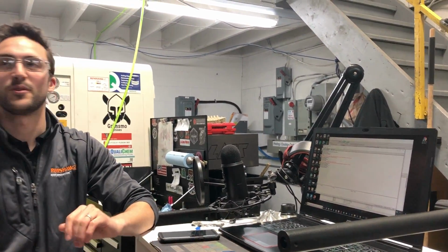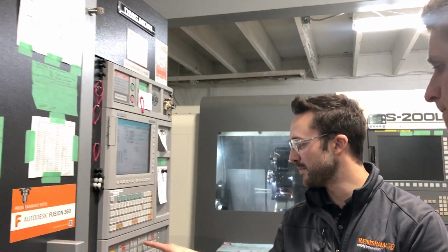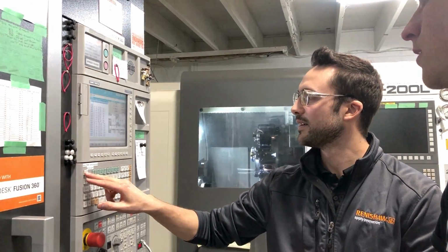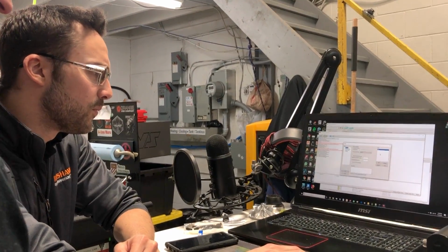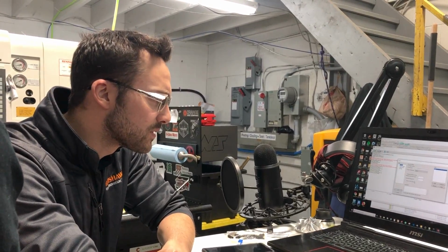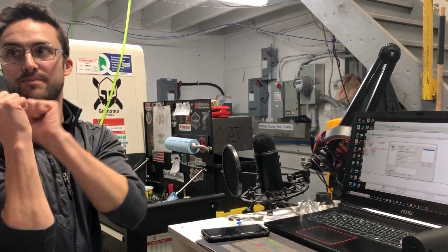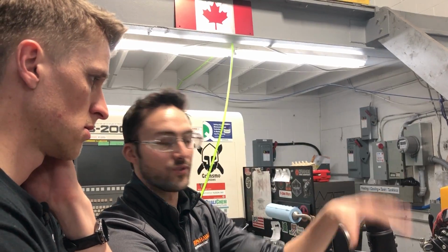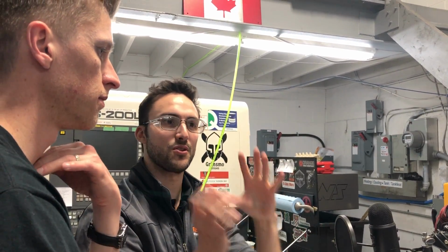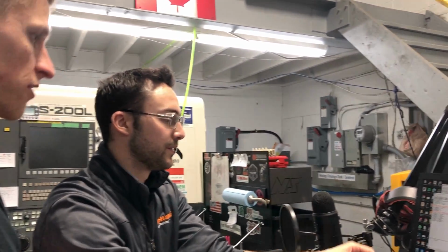So if we have a successful login, if we pull up your program, was that in memory? Yep. Now what's important here is you have user groups. We need to make sure that we have the right user groups. Basically, when this user, which is what we've set up in the CNC, logs in, it automatically uses these settings. So it'll put the file in different locations. You could have 5 machines hooked up, but going to different folders on your computer through the same FTP server.